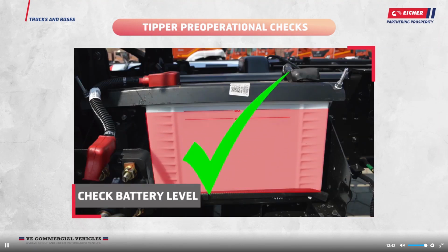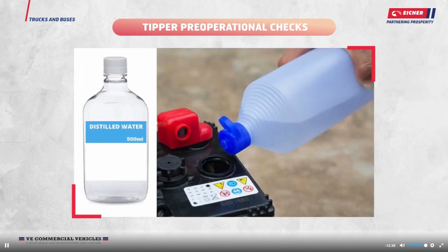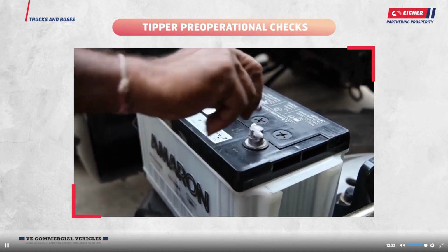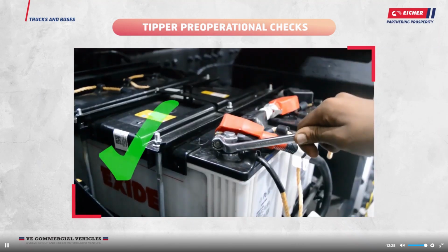Check battery electrolyte level. If the electrolyte level is low, top up with distilled water. Check for corrosion in the terminal. Clean with warm water and apply petroleum jelly. Also, check that the battery terminals are tightened.